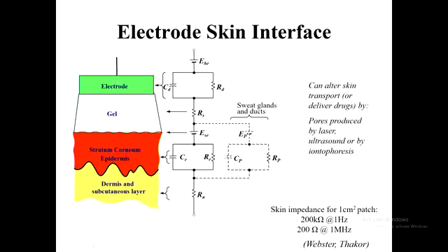Mostly we'd expect the capacitive element to be in charge of charge carrying behaviour. The gel is here to provide some conformal contact with the skin surface, and there are various layers of skin till we get down to the internals of the activity that we're looking for, which is the site of the origin of the biopotentials.